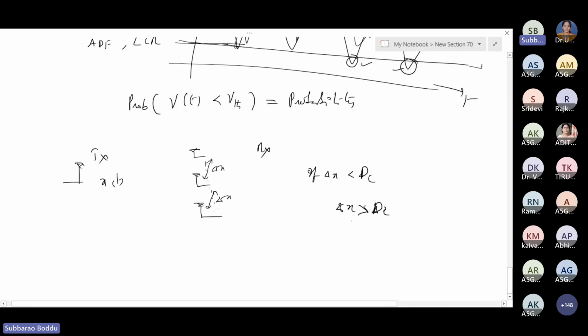When the signals arrive at the antennas with equal probabilities, that is where you can write p of theta is 1/2 pi, which follows a uniform distribution. Then we calculate the correlation function. The signals received at antenna 1 and antenna 2 are uncorrelated, which means my correlation function is going to be 0. Suppose you are receiving one copy at antenna 1 like this, and another at antenna 2, something like this.